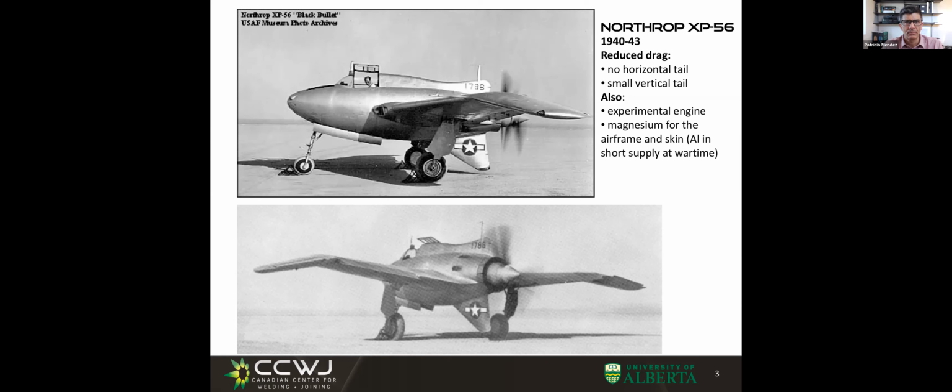So the distance between the tip of the tungsten and the surface of the weld pool, that is what is called the arc length. And so if I pull the tungsten back, I would have a longer arc length. If I push the tungsten in, I'm going to have a short arc length.